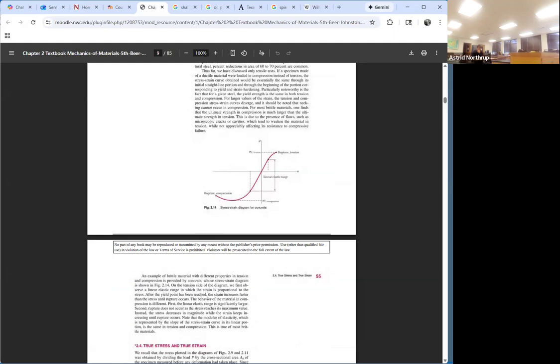And another thing that you want to do, put this up on the board. We'll study this later on, but it's an excellent question. If you have a concrete slab and it's flat like this, it works very well. If you load it and it bends like this, the top part of it works very well and the bottom part does not, because it goes into tension. So there's a place which they refer to as a neutral axis where the stress is zero, where it shifts from being in compression to tension.